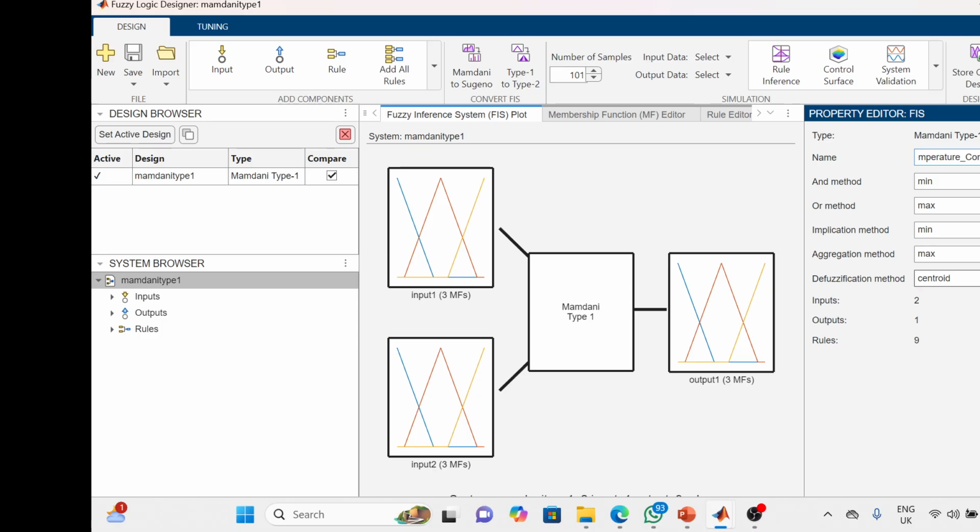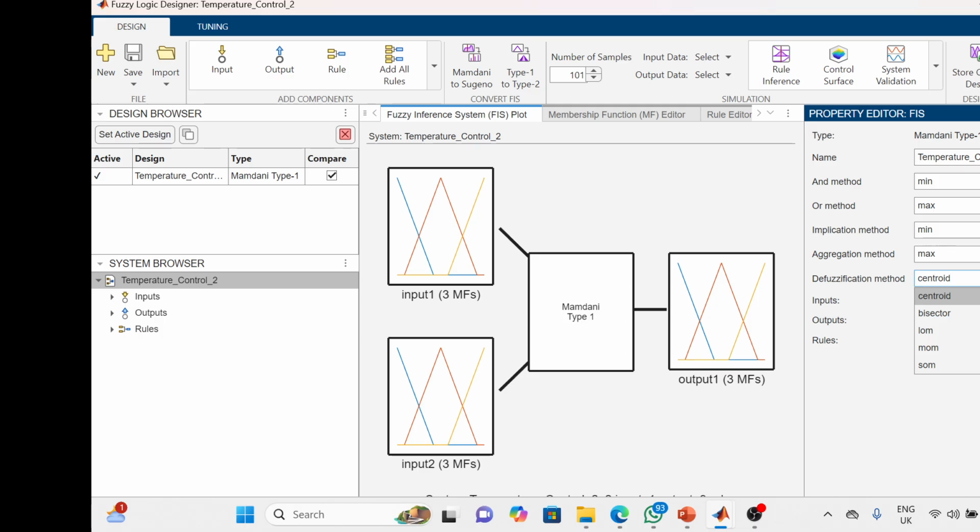Then the defuzzification method, I've told you that we have different types of defuzzification methods. For us to be able to convert the fuzzy value obtained from the inference engine back to the physical value that can work on the system. For instance, here we are working on an AC system, so for the system to be controlled so as to determine the level of cooling power in the environment where it is placed, we need a method that is going to do that for us.